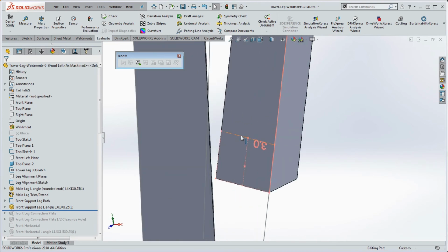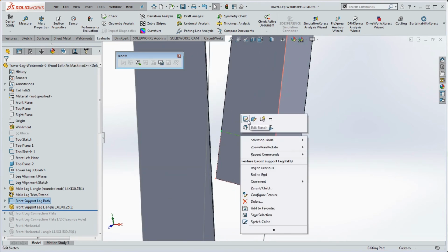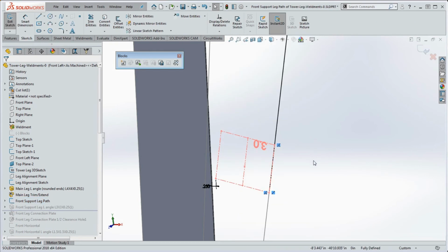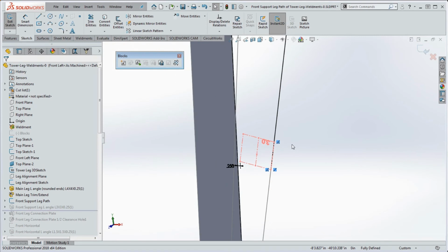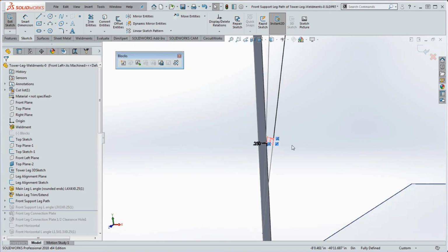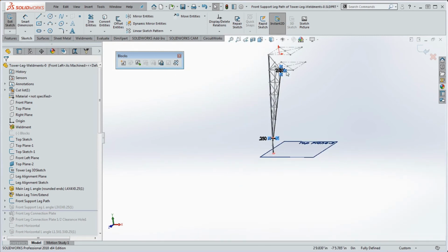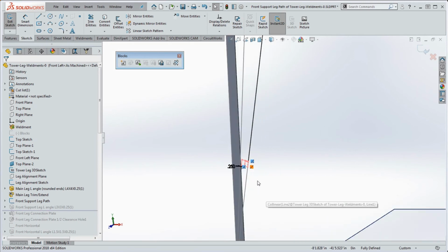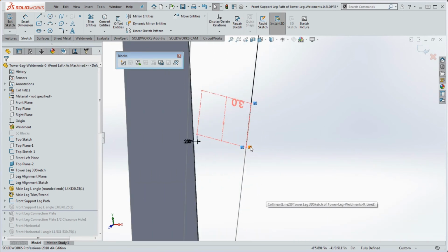If I take this 3D sketch line in here, or that pass segment line sketch element in here, and take a look at that, we have a 1/4 inch offset from that block, defining that first. We have 2 coincident relationships in that block on that pass segment line, which you already defined in that super block I told you. And then we have a collinear, here it is. Here's a collinear relationship or coincident relationship in here.